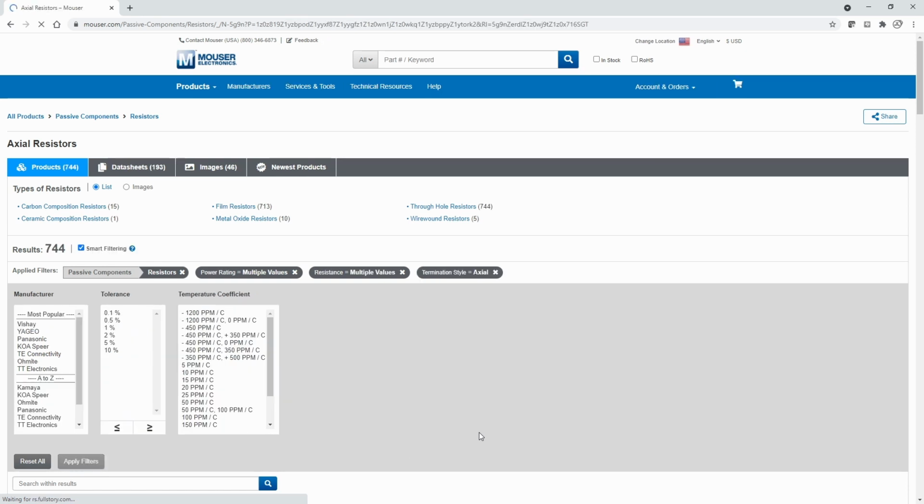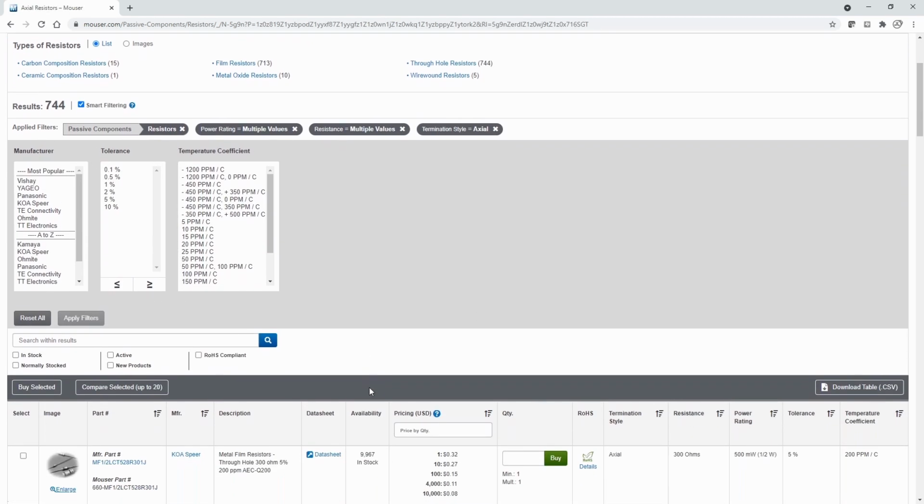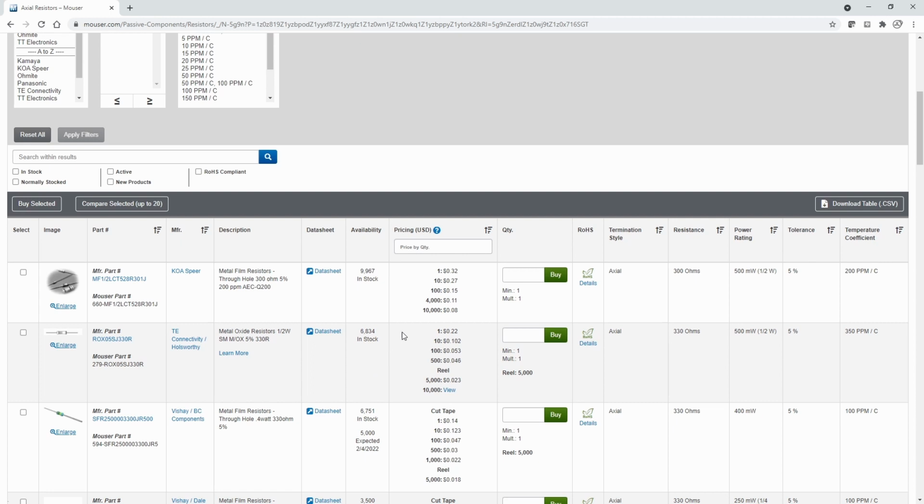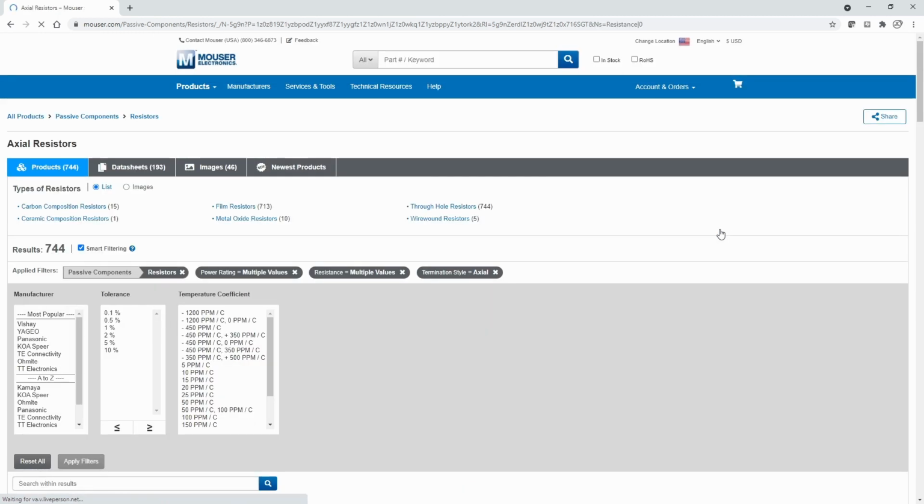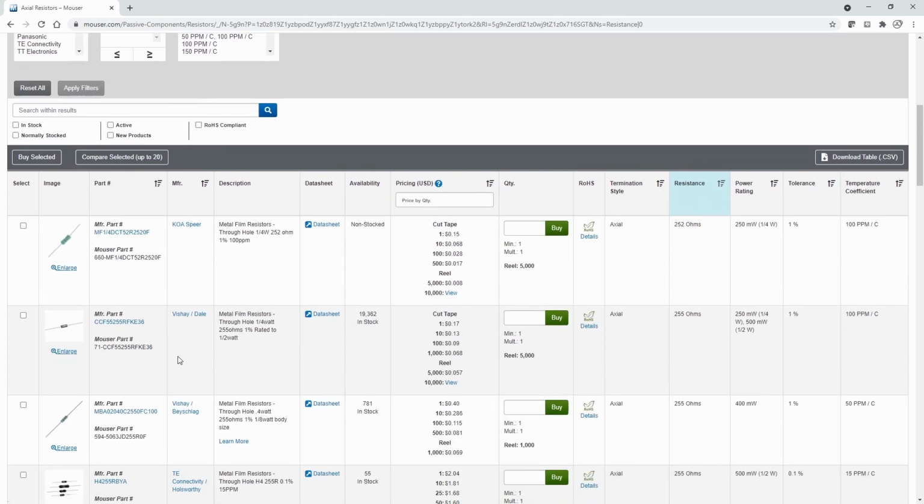And I'm going to first sort by the resistance, because I set the bottom at 252 and then I went up from there. I chose not to go down from 252 because that would increase the amount of current going through our diode, and we don't want to do that. If you remember what we did with our 50 ohm resistor earlier, that gets well over the absolute maximum rating of the device. So 252 is where we're sitting right at the abs max when our battery's fully charged.